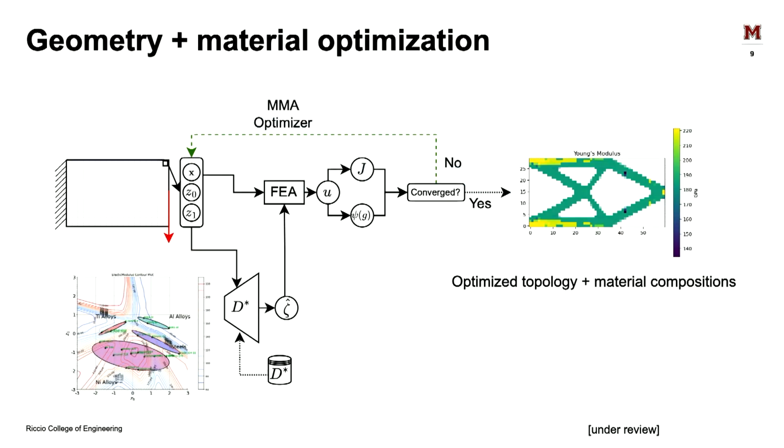And this is the template of how we would integrate continuous and discrete design variables shown in this figure over here. We can continue to use density-based methods to do your topology optimization of the geometry, and then you can bring in this continuous representation of catalogs to, for example, in this case, select the material, and finally you can iterate through gradient-based optimization and then penalize the distances of the material location to snap towards real material. So this is a template of how we can integrate discrete catalogs with continuous